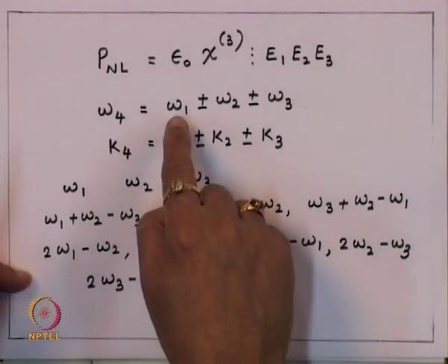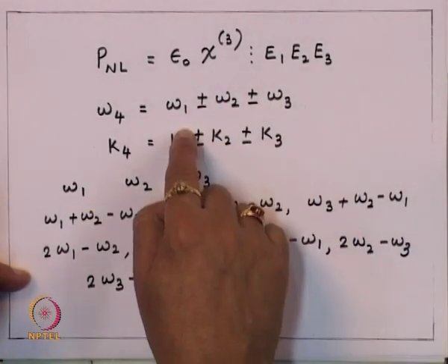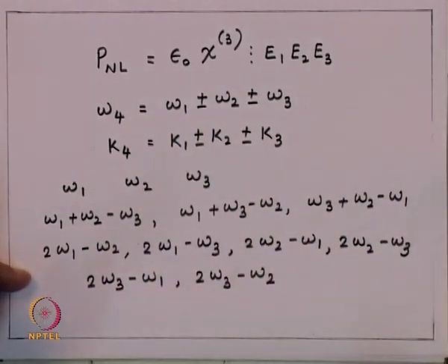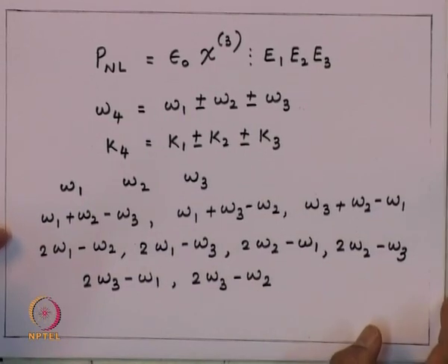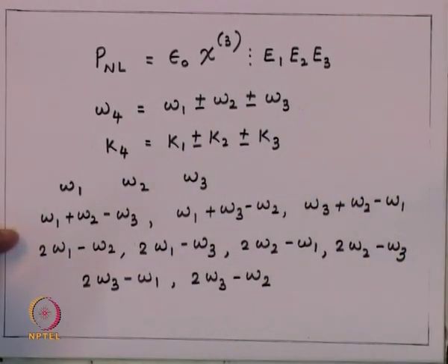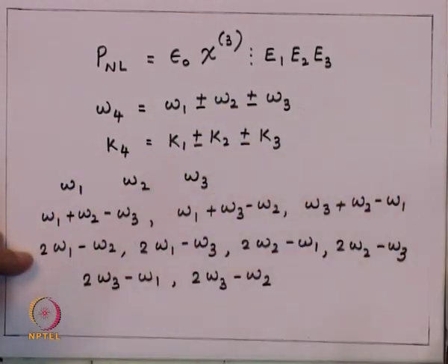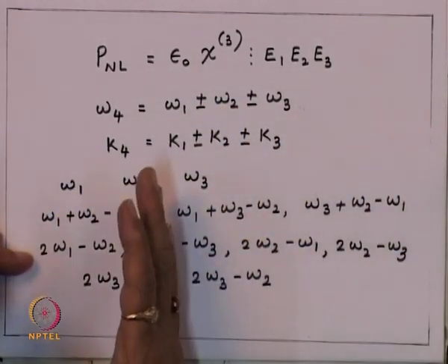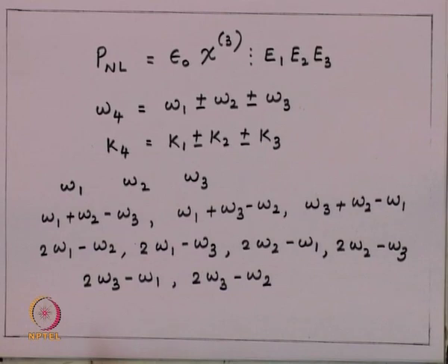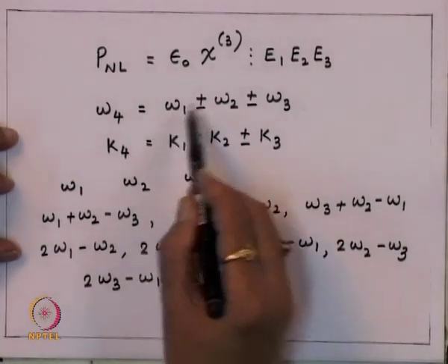We may have a frequency omega 1 plus omega 2 plus omega 3, but this frequency will be approximately 3 times omega 1. So, that will lie in a totally different frequency band. This combination is going to create many more frequencies, but those frequencies which are double or 3 times any of these frequencies we are not looking into, because they lie in a different frequency band and very easily they can be eliminated by a filtering process. But these frequencies all lie in the same frequency band.